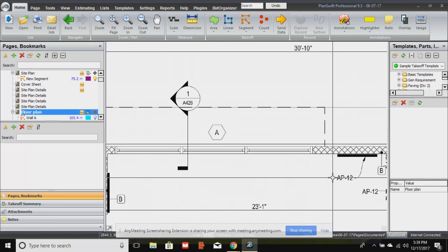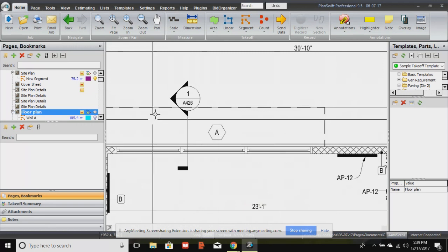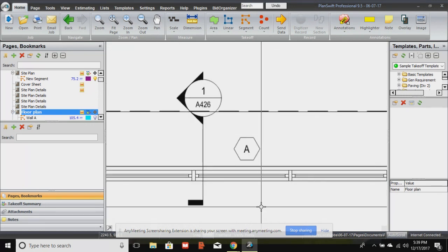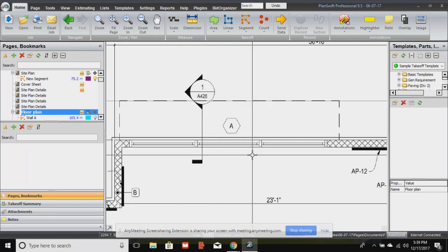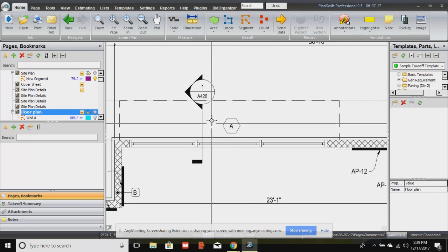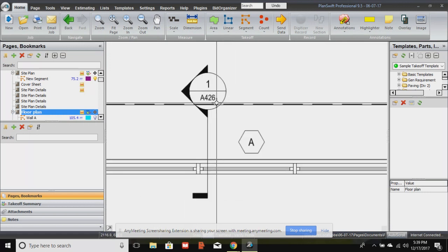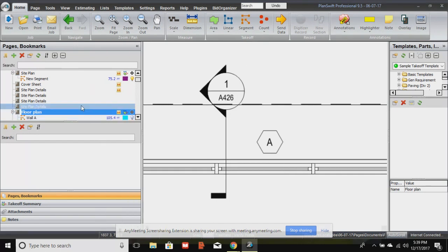Okay, so remember, we're going over the 4 views. Plan view, we already looked at. Most basic view, like you're hovering over it. Our floor plan took us to a section view marker. And how you read that is you're going to go to image at the top, page number at the bottom. So what the architect is saying to me, by putting this marker right here at window A, they're telling me, Stacy, I need to show you the wall construction now, not how long the wall is, but the actual wall construction, and I can show you that at window A if you go look at picture number 1 on page A426. So let's go to that now.